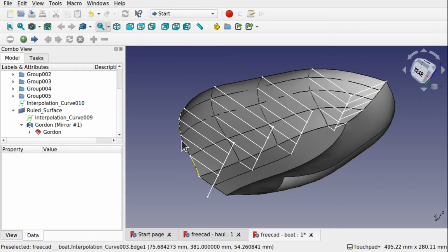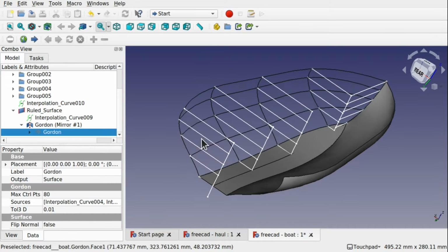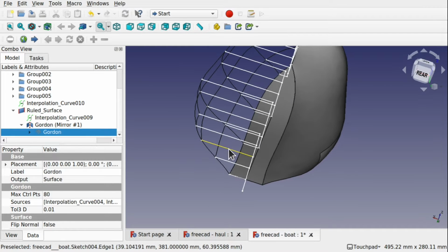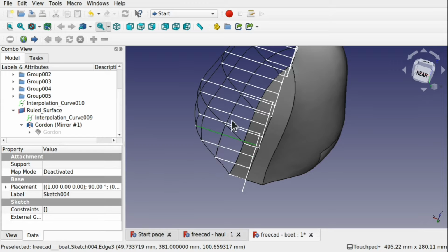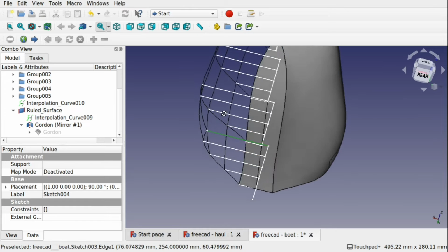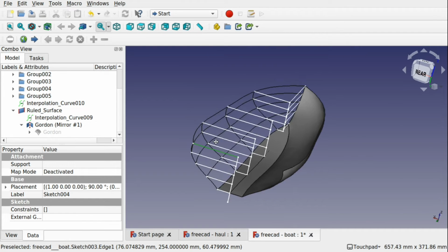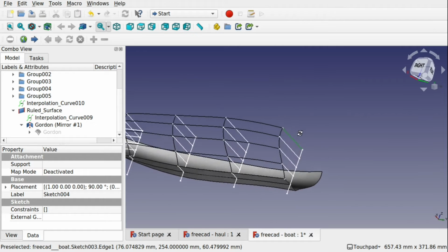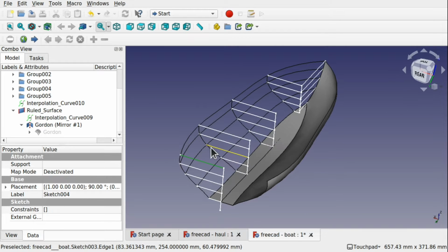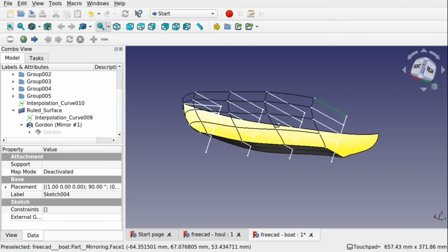So you can see these points have a curve that runs down them, both along the horizontal and the vertical, and these attach to each of the points of these lines of the sketch, and we can adjust the size of these lines, pulling in these curves and adjusting our whole width and dimension and shape to create the desired effect that we want. We can even place these into a spreadsheet if we so desire, so we can control the size of these arms to control each of these planks going through this ship hull.